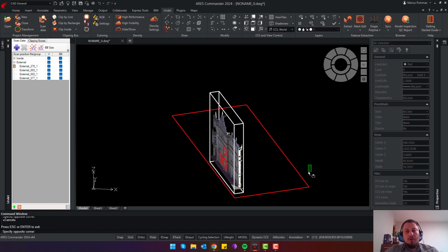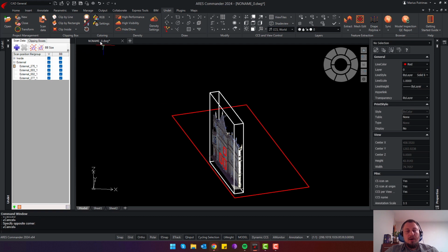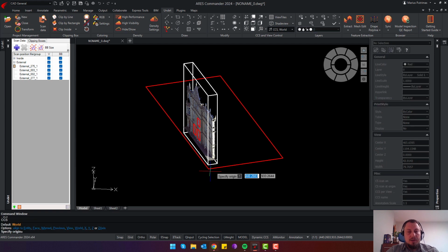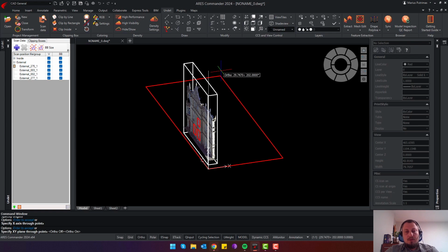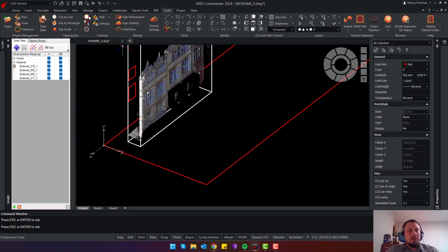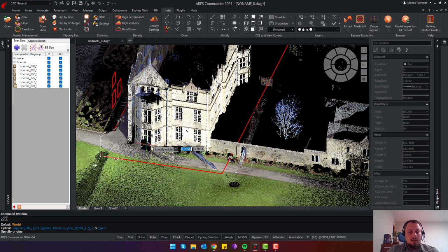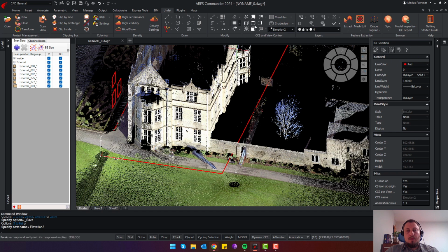And if you have 4 elevations, you can copy this master file and make a copy for each separate file. And when you have these lines, you can very easily set up a new UCS for each reference line or each separate elevation projection. To save the UCS for the second elevation projection, we can type UCS and S, save, write the name elevation 2, press enter, and now we have saved UCS elevation 1 and 2.